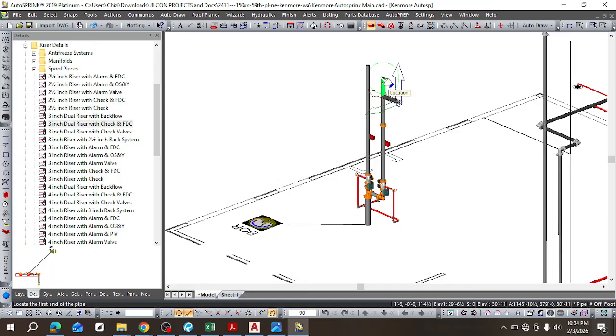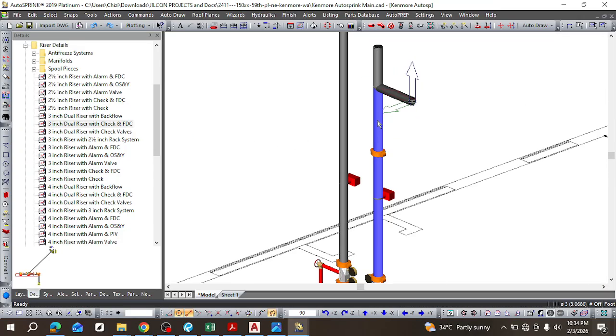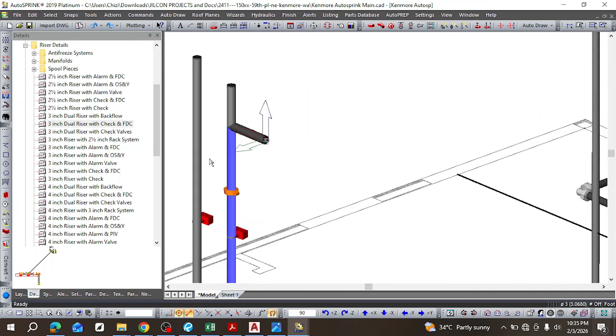Okay, this is what you are playing with. So what I wanted to do is, after selecting the pipe, you press shift and press your scroll button. You get to select the size of the pipe. It's 3 because it's a 3-inch pipe. If you change it to 1, it changes, right? So Control Z is helpful when you are laying out your pipe. As you just finish, you hold your shift and press your middle button and you select the size of the pipe you're drawing.